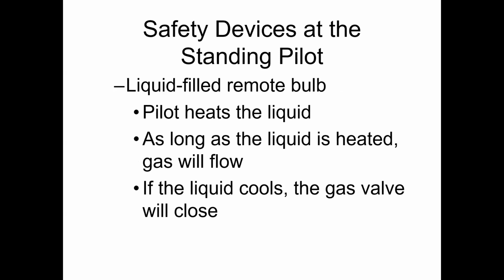And it's probably the oldest style of this because it's the most basic, all right? Here's the idea. You put liquid in a little cylinder, and then you have a thin line carrying that liquid up to a diaphragm, all right? If that liquid is heated, it will expand. It will push on the diaphragm. It will allow for gas to flow through to our pilot, and then it will continue that process.